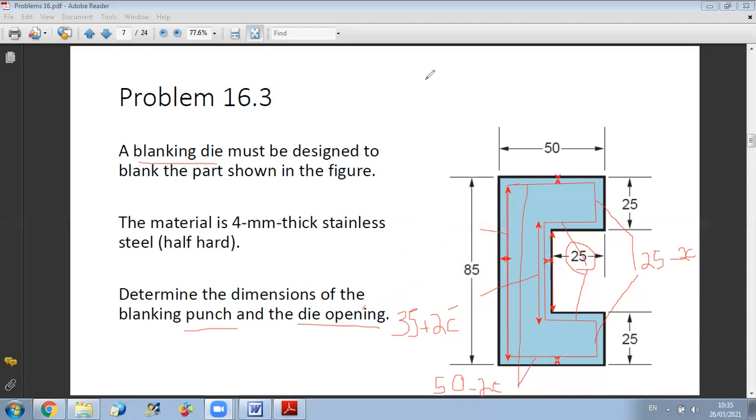No, guys, no. Here we don't have the die and we want to make a hole inside. Here we have a work part. Look, don't confuse between the two operations. Here the idea is, yes, it's true that in an operation you will always do like a hole. But here the final product is not a part with a hole. The final product is the blank part. This part will be cut from the operation, and this is the final part you want to have.